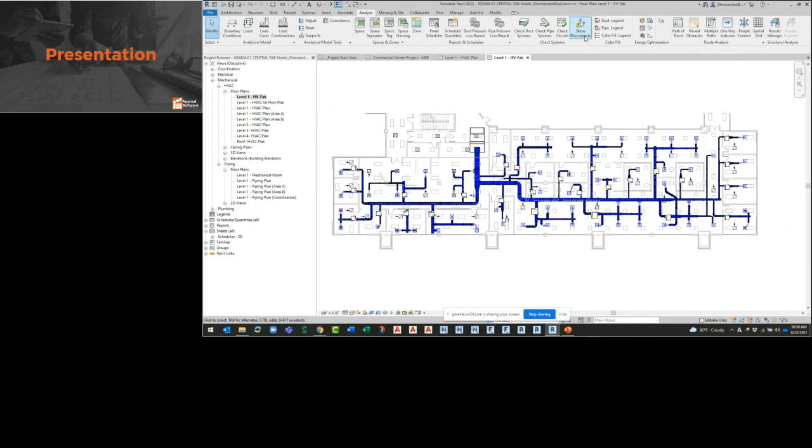And check the disconnects, make sure what's been broken or where all my disconnects are, or what I've got to repair. But before I repair or fix any of the conversions, I immediately select all and optimize links. That's going to, again, improve the performance and get rid of a lot of the simple warnings, and then the rest, what's left over, I'm going to have to go and fix myself, and those I can track down.